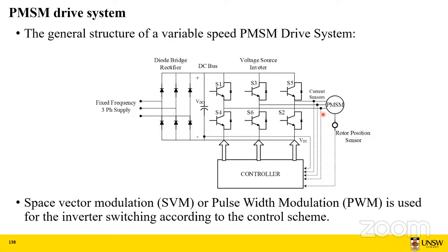In a conventional synchronous machine, you have damper winding. So the synchronous machine actually starts like an induction machine, and then when the rotor aligns with the stator's rotating field, it starts to rotate at the synchronous speed, because we are providing the field current to the rotor.